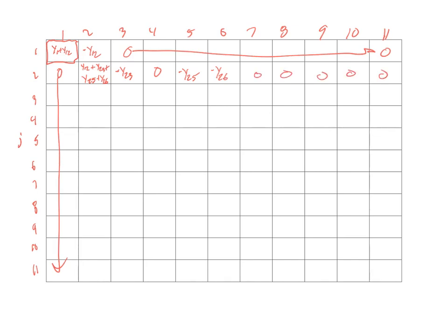And a nice way to check is if you look inside this element here, you can see that you have y12, oops, and I made a mistake. This is a good way to check, right? This is not 0. It's a symmetrical matrix, so I actually should have put y12, and then I start with a 0 here. So you can see by having it set up like this, you can actually help check yourself. There is a y12, so that means I should subtract the admittance between bus 1 and 2.